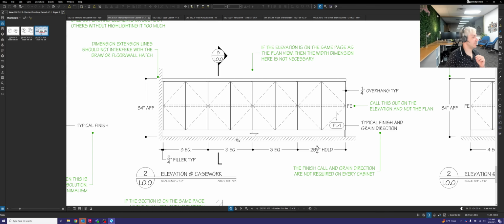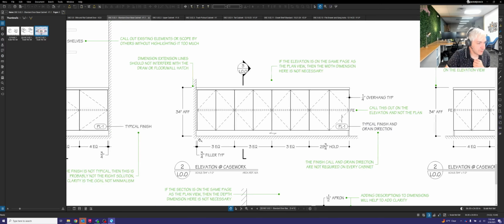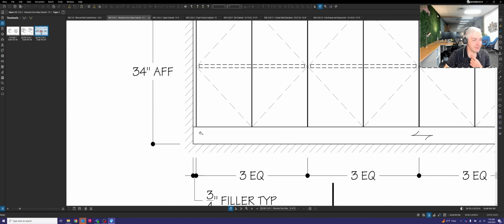I'll try to include a picture of one of those here if I can find one. But anyways, when you have an inside filler, meaning when you have two cabinets that are 90 degrees from one another on the inside corner of a kitchen, you're going to need a filler that is 2 7/8 wide. Now that's 2 7/8, the actual filler size. The seen part of it.